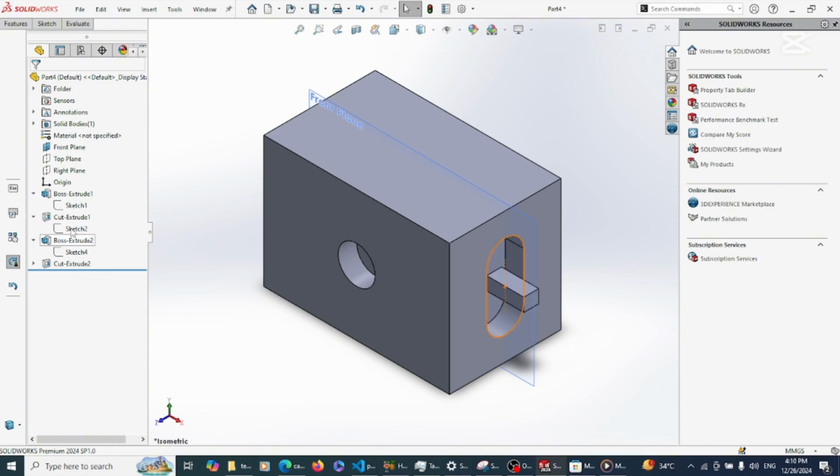Another thing to also know is this. I can do what they call rollback. See what I'm doing? I'm dragging this line. How did I do that? Once this hand symbol appears, I double click or double click and drag my mouse up. Another way is, when that symbol shows, I hold left click on my mouse, on my touchpad right now, and I'm moving.